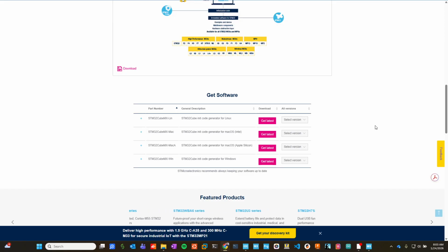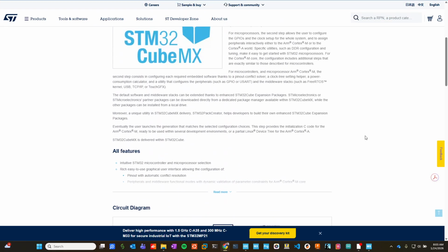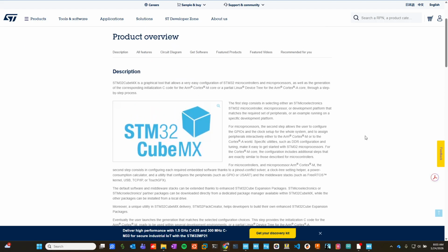So I'm assuming you can go off and get those installed. You may have to download some packages when you're generating. Especially when we do this for the first time, you won't necessarily see that when I do it, but your system will have to go out and get the L432 libraries if you follow along here. The first step is that we're going to fire up CubeMX and create a template project. That's where we're going to start working.